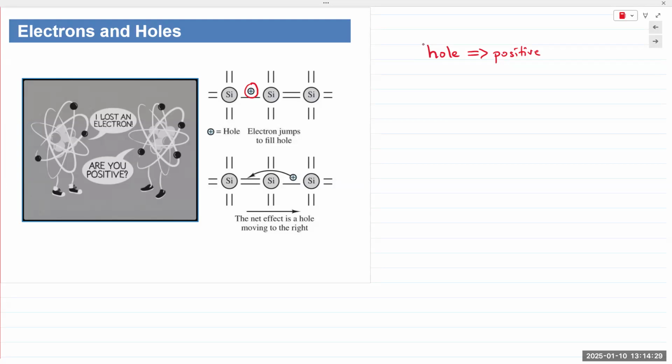Temperature rises to room temperature, which is basically this environment right now. The electrons have acquired enough thermal energy to break free of their bonds. Once they break free of their bonds, they move out of their spot and leave behind an empty spot. These electrons are free to move around. The number of electrons that are free to move around is much larger than are present in an insulator, but far less than what is present in a conductor. So hence a semiconductor, it's somewhere in the middle.